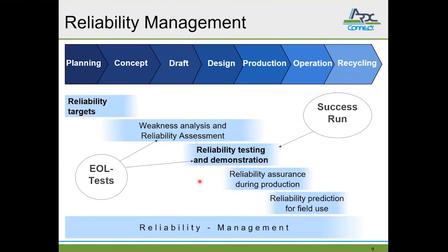Before we get deeper into the whole test planning procedure, we will shortly address the main difference between the so-called success run testing and the end-of-life testing. A common pitfall is to think that success run testing is necessary when it comes to reliability demonstration, but it is not. You can also use an end-of-life based test strategy to do your successful demonstration.